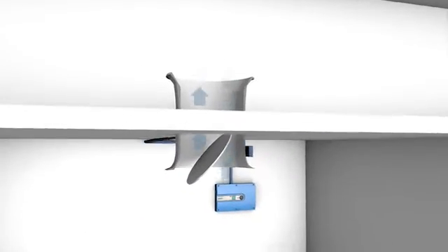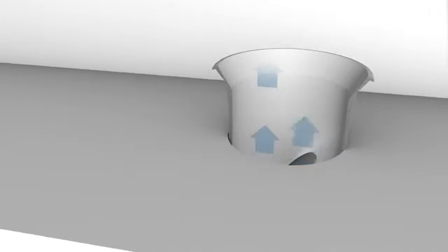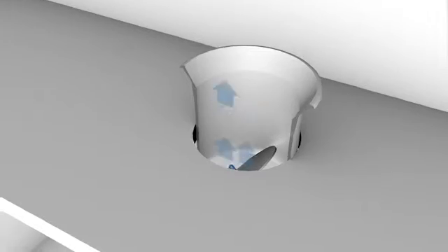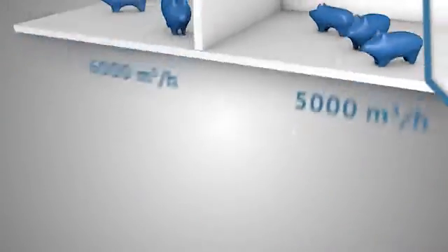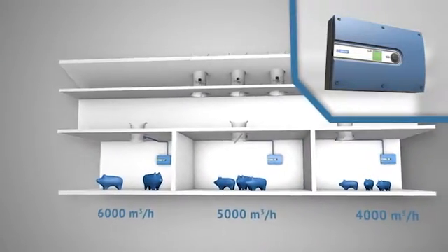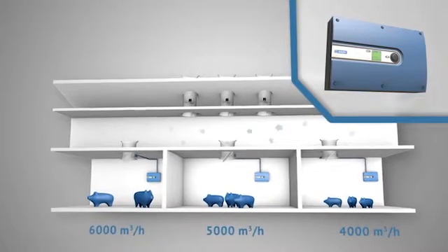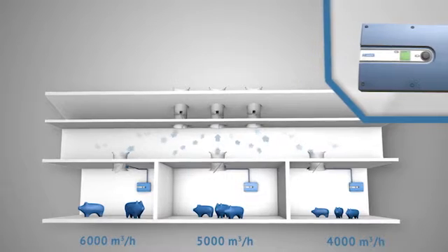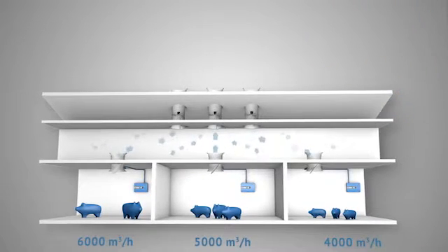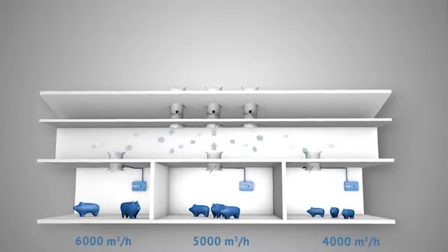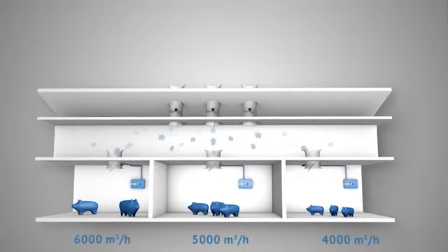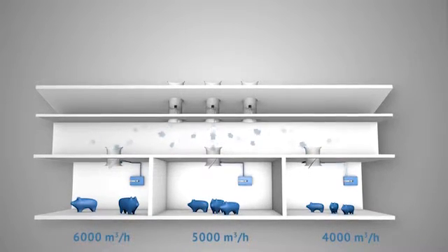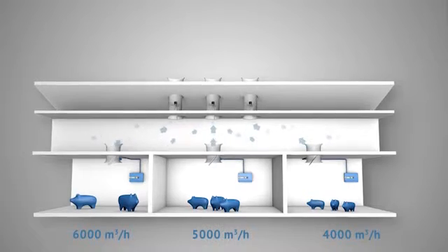As measurements are carried out without the use of movable mechanical components, air resistance in the chimney does not increase. The pressure in the duct is maintained by a climate computer and is regulated via a differential pressure meter. The online measurement allows the pressure in the duct to be regulated even more closely to the actual requirements in the sections.